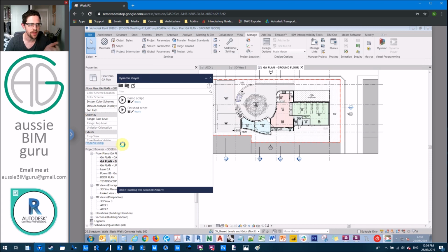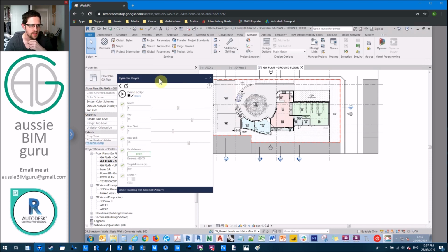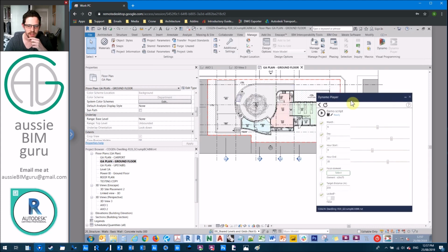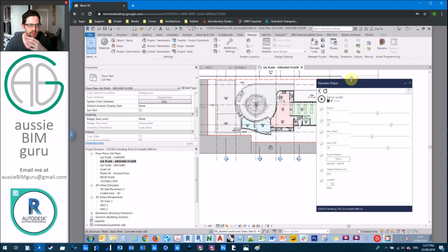The annoying thing about 3D views in Dynamo is you can't assign 3D view templates to them. Such a pain. I think there are some really harsh workarounds by going into the object classes that I've read about, but obviously for the average user that's not possible. So what I recommend is usually applying the view templates after the views are created.